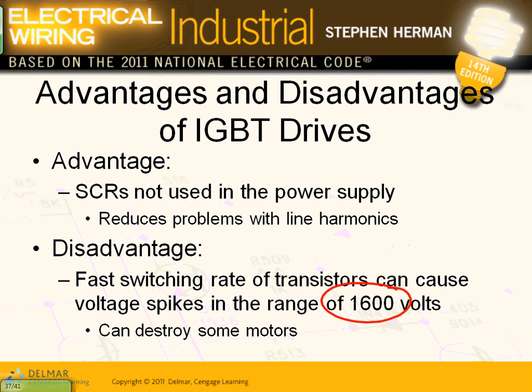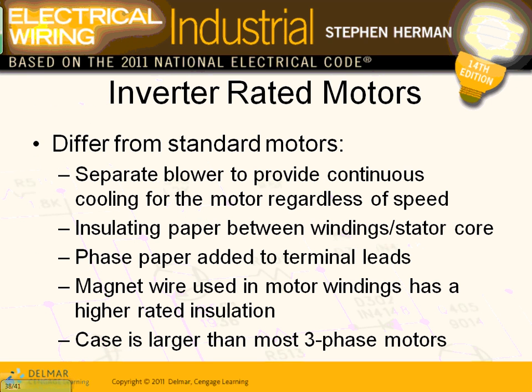All this, guys, happened with the manufacturers. So we have IGBTs as a technology. All you care about right now is buying an AC VFD that controls it. How does it do that magic? AC, DC, control the DC, spit it back at the right frequency and voltage. Here's my motor, here's my VFD, here's my system.